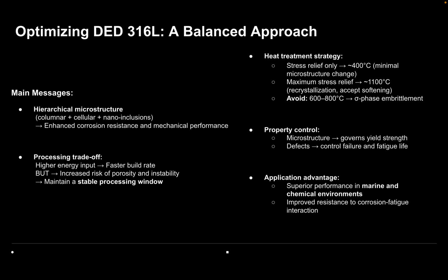Optimizing DED 316L requires a balanced approach across multiple factors. First, the hierarchical microstructure provides a strong foundation for both mechanical strength and corrosion resistance. Second, there is always a trade-off in processing. Higher energy input improves productivity, but increases the risk of defects.